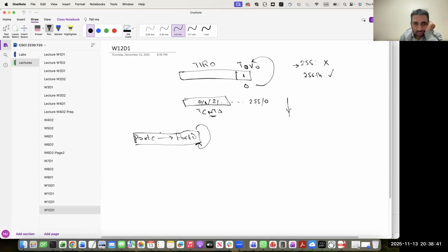So I want my microcontroller continuously doing this, right? But before I entered this loop, I set the timer. I initialized the register with a value of 0 and I started the timer. And now I started doing this. But what I also want is that when this flag is set, when the overflow has happened, I want to immediately go to a program which performs some action, for example, generating a square output on, let's say, the PB5 pin.